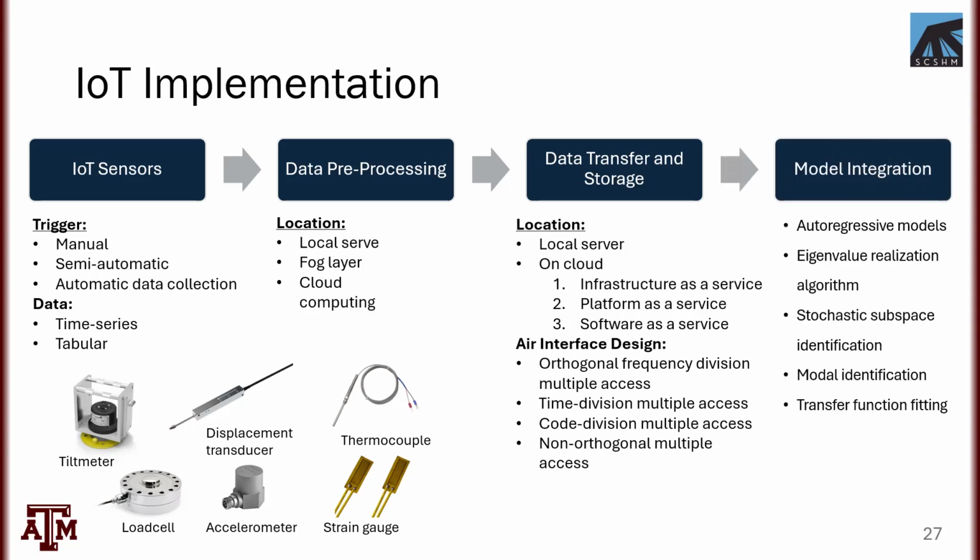And finally, we perform the classic system identification and model integration, right? All those autoregressive methods, the eigenvalue realization algorithms, the stochastic subspace identification, modal identification, transfer function fitting algorithms, all those things. So most of what you're seeing here is classic SHM. We've been doing it for a while.